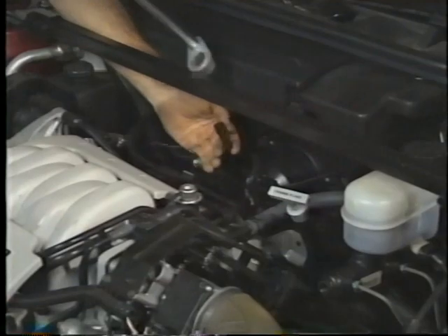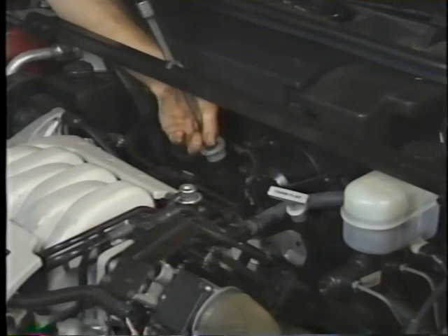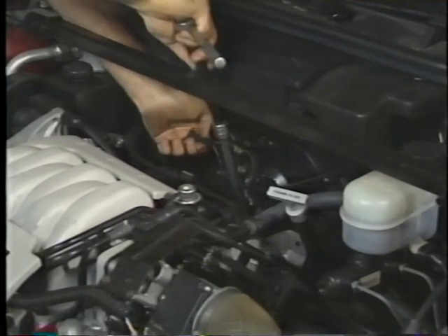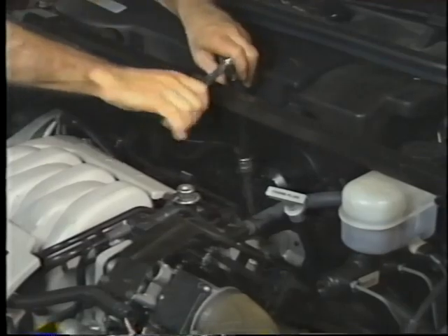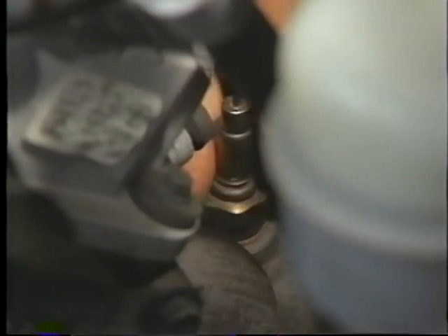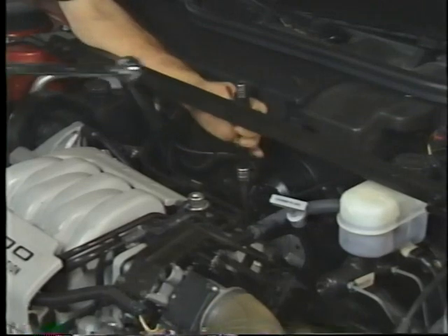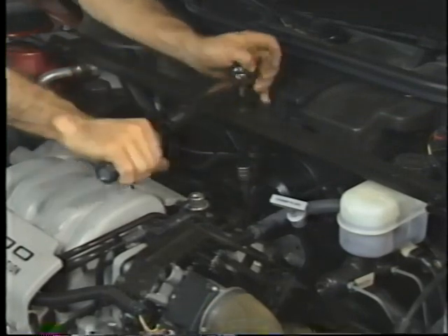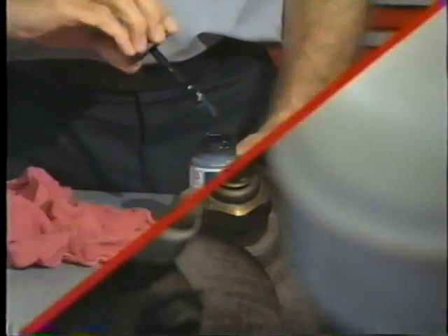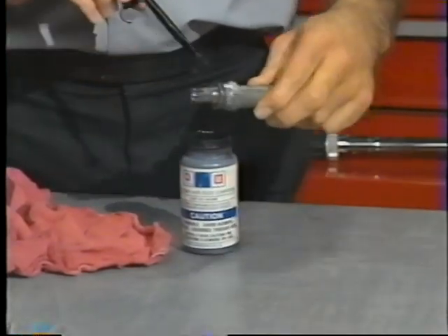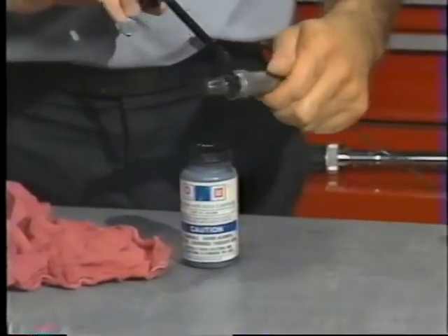To remove an oxygen sensor, disconnect its wiring. Then use an appropriate wrench to loosen the sensor. If you have trouble unseating the sensor, run the engine for a few minutes to warm the exhaust manifold, then try again. When you install a new sensor, take care not to drop it. It's possible to damage the element. Screw the sensor in finger tight, then use a torque wrench to tighten it to 30 foot-pounds. If you're reinstalling a used sensor, first coat its threads with AC anti-seize compound.